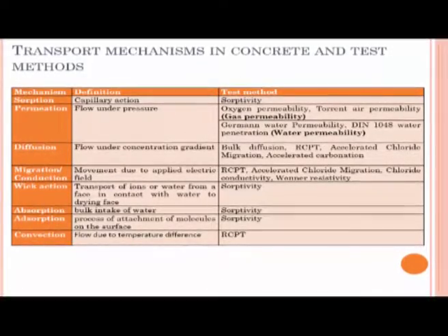Now, if you really look at something which is common to all these systems, you will realize that all durability problems require the presence of water. Without water, concrete will not have a durability problem. In terms of durability, the component that causes the maximum damage is the presence of water. So, if you have water available in the system, or if water comes in from the outside, that is when durability problems actually occur, alright.